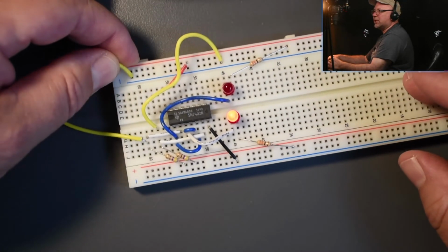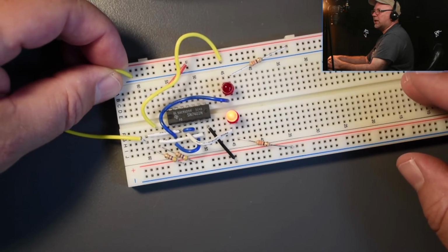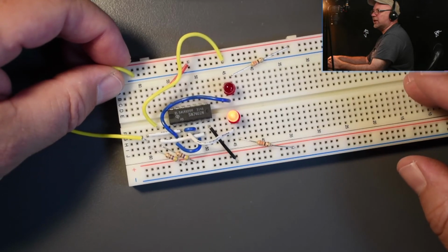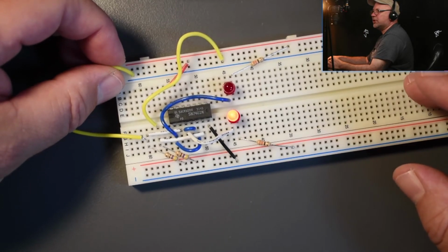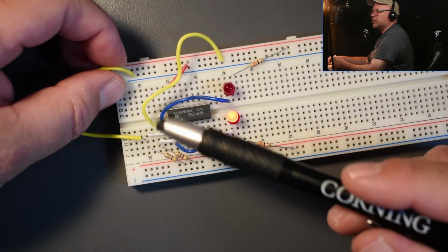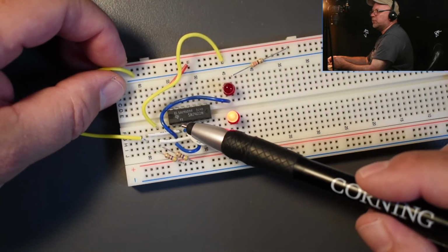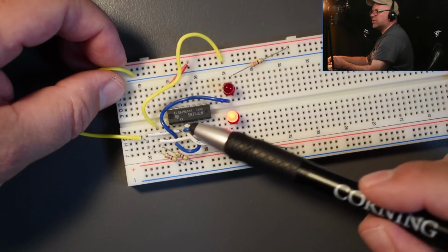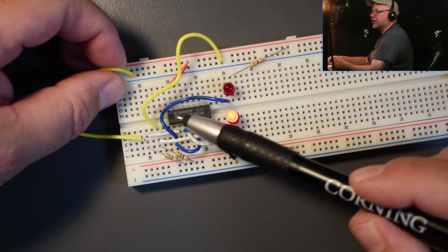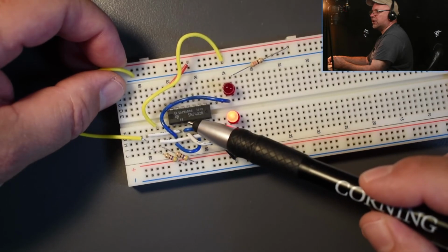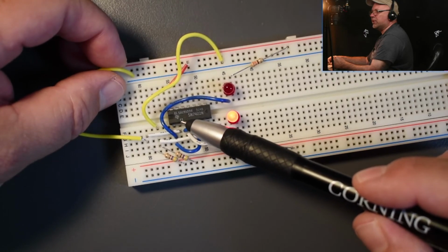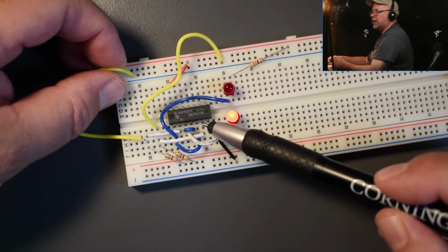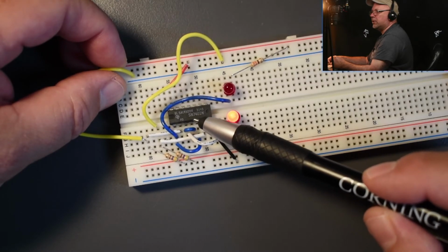When I remove that wire, if you look at the schematic, it's a pull-up system. I'm going to disconnect the ground from that input point, and through these resistors one of the inputs of this NOR gate will go high. There are 2 NOR gates, arranged input, input, output, and here is input, input, and output.